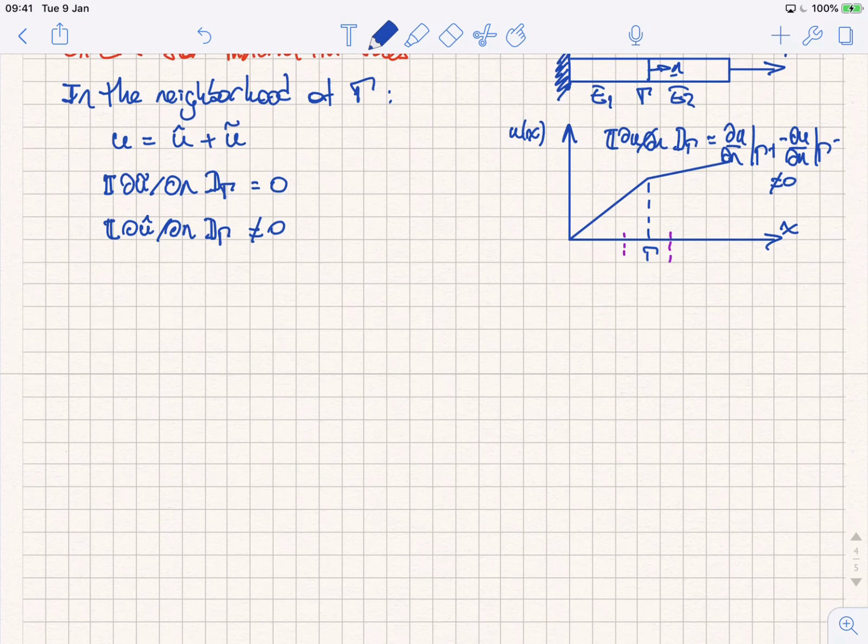the GFEM framework, and we're going to say, as we said the first class, that GFEM is a procedure to paste together different types of approximations. Remember that we talked about clouds, or supports. Who remembers what a cloud or support was? If I give you a node X alpha, the support of X alpha was? All of the elements which are connected to it. Yes, all the elements that were connected to that node.